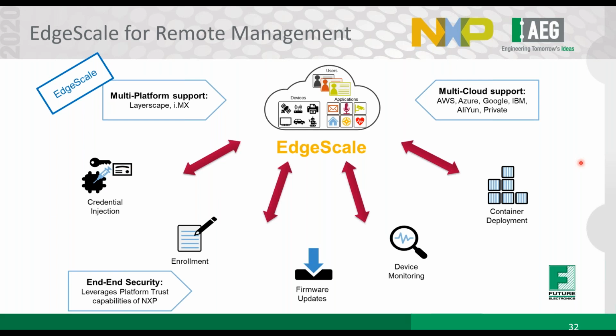And basically, when you ship a device to your end customer, they would register that device against the portal, and the device would authenticate itself against those manufacturing records that were created. And if those records match in terms of the unique ID for the box and the security keys, then it will proceed to the next step, which is the enrollment, the provisioning, allow the firmware updates and the applications to be deployed on the box. And if it's not authenticated, then basically it's just going to be a brick. It's not an authentic device that belongs to you, that you would have shipped with your security keys. So nobody's going to be able to use that device.